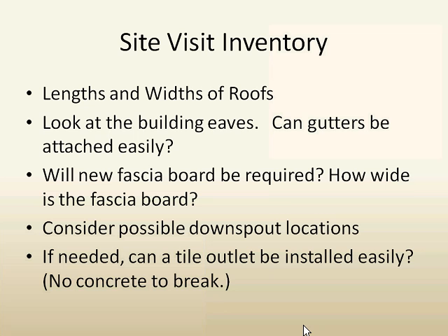And then think about, could you do a tile outlet? Could you do a gutter drain or an infiltration drain? Is that a possibility? Is there room for that? And can you keep livestock away from the eaves of the building?